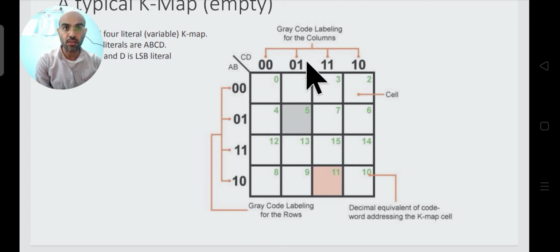This is how you reach a particular cell. You identify the presence of a certain min term, and then you fill it in at the particular place depending upon the decimal equivalent of that min term. That is why in the canonical form expression we represent the min term with a certain subscript. That subscript should match with this.